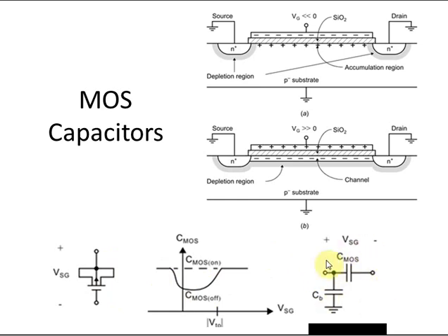Now where's this coming from? Well, clearly there's the capacitance that we're interested in, between gate and body, source and drain. That is captured by CMOS, and that's what's being plotted here. This is a plot of CMOS versus voltage. But there's another parasitic capacitance between the N-well in which this PMOS device resides and the P-type substrate. That's a parasitic capacitance borne almost entirely by this terminal of the varactor, this terminal of the capacitor. So that's modeled here by CB. It's a lumped capacitance between basically the body terminal of the PMOS device and the P-type substrate. So this is a good model for that.